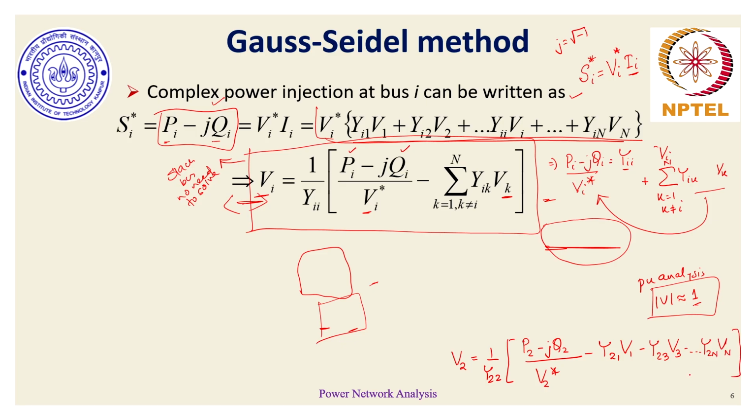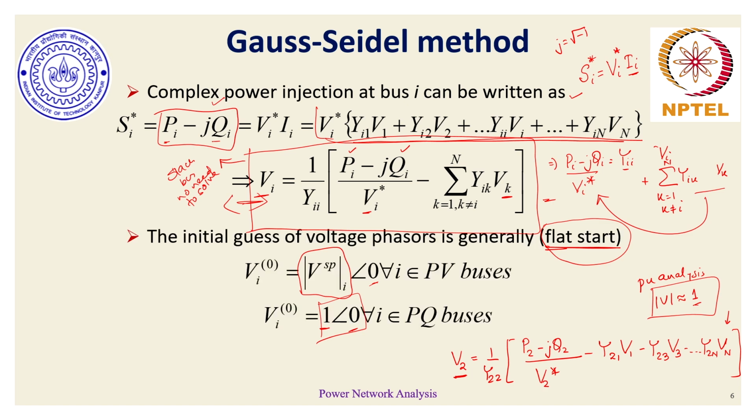And while I am trying to solve this equation, essentially I am trying to find the value on the left hand side. And this left hand side value can be known when I know the initial values of the right hand side quantities. With the flat start as my initial choice of values, I very well know what V2, V3, Vn are. These need not be the final solutions.